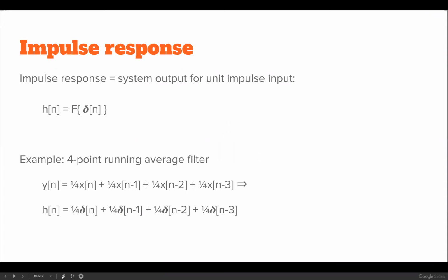Most important response for a digital system is an impulse response. The impulse response basically defines the whole system, what it is all about. On analog systems, you would do some system analysis using the step response because the impulse is quite hard to make in real life, but in the digital world, this is a piece of cake.